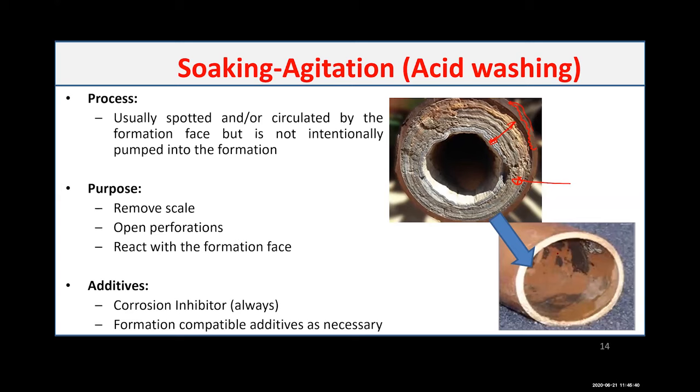It can also help to remove any scale from the perforation. And sometimes some of the scale will be at the formation face, so we can pump the acid to the formation face. Again, when we are doing acid washing, our intention is not to pump it inside the formation. At maximum, the furthest location is just the formation face.